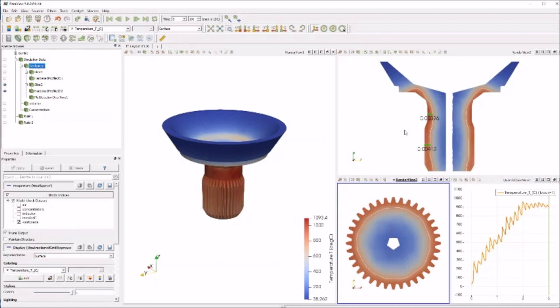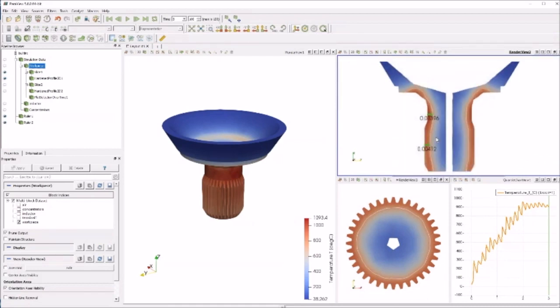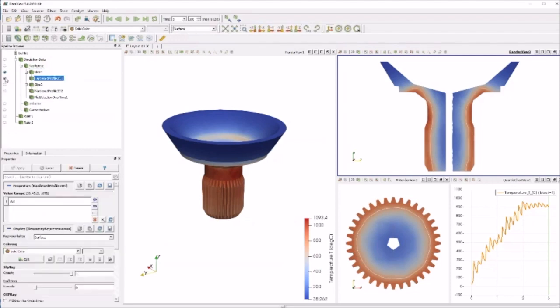The same, you can see here the temperature field. You can also change to another field. Here, it's not a problem. The most important is this white line. This line represents the hardening depth. Without this line, you can see it like this. However, we just apply the hardening profile filter, and we see the region which is hardened.